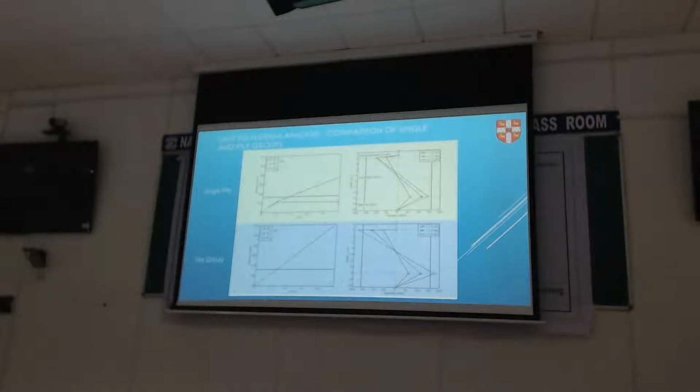We're just saying this single pile, I can do this calculation. I got a pile group, I can do a frame type calculation of that and compare one to the other. So what this says is, okay, I got this non-liquefiable crust on the top. So that is a single pile. So my bending moments are shown here along with the deflection I'm getting there.